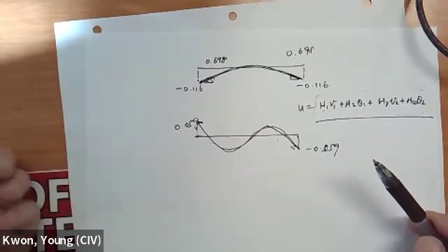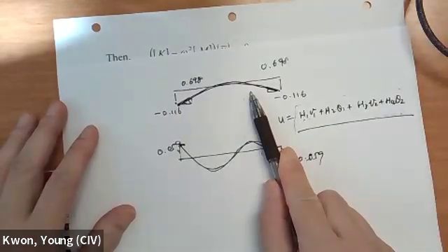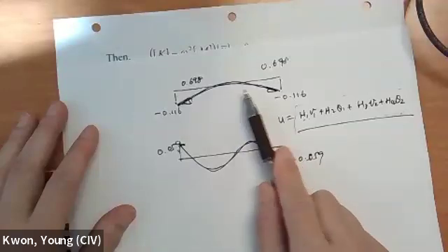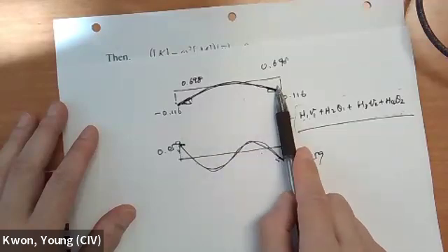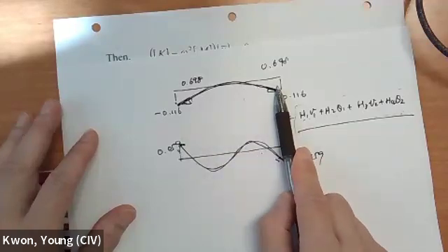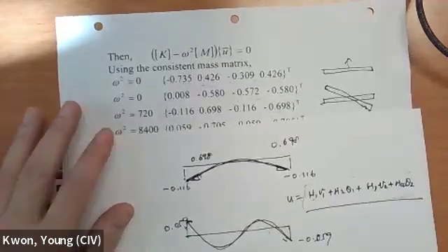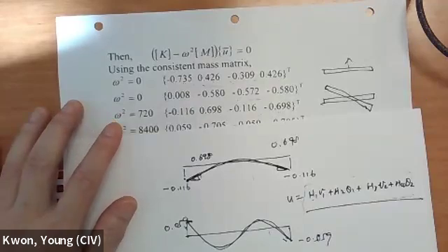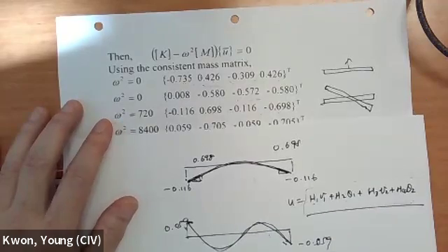On the other hand, if the mode shape is simple like that one, then you don't need so many degrees of freedom, nodes or elements to represent it properly. So naturally, the lowest mode shape and natural frequency, the eigenvalue, are more accurate than the higher ones. And that's also what we are looking for, because the lowest eigenvalue and eigenmode are more interesting to us.